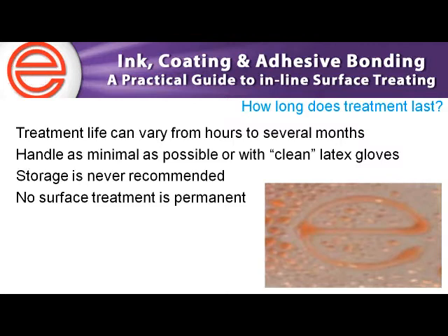It's always good to handle the parts as minimally as possible, with clean latex gloves whenever possible, by your operators. Storage is never recommended. You just don't know what kind of results you're going to get if you do treat and store a part. It's good to do everything in line. And of course, no surface treatment is permanent. It may take a very long time to wear off, but it will wear off over time, unfortunately. So that's why we do want to set up that treatment right before bonding.